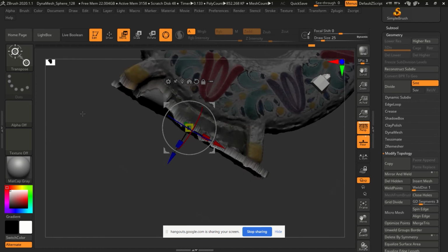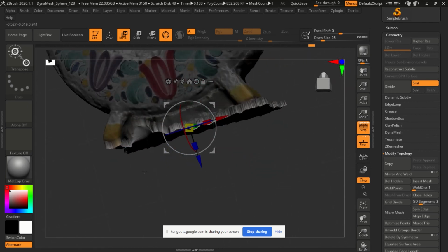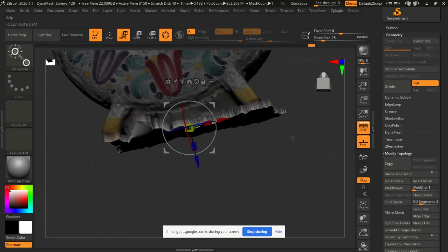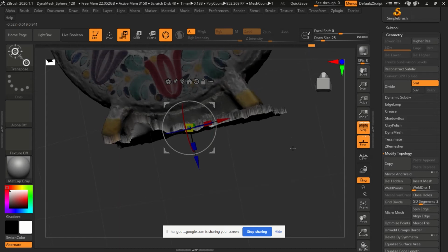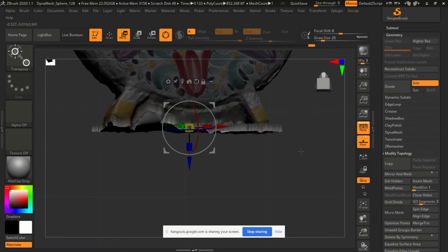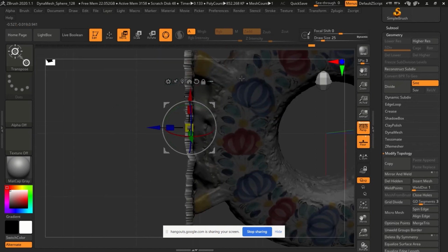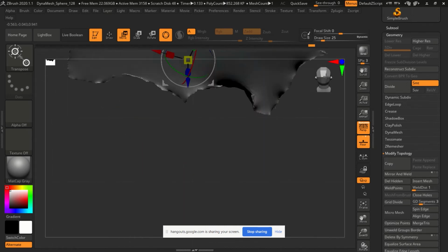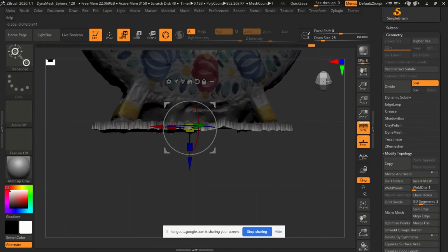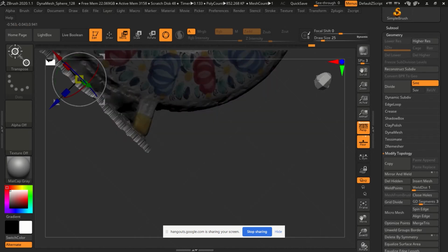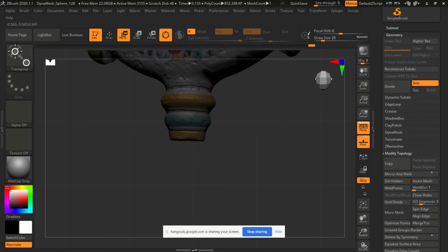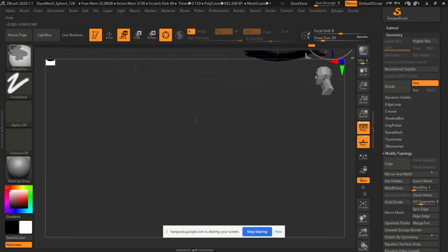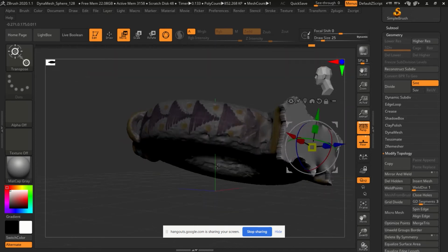If you want to snap to a view while you're rotating, so maybe this is a little annoying, while I'm rotating, holding right click, I can hold Shift and it'll actually snap to 90-degree angles, right? That's similar to what using this model is doing. It's snapping to 45-degree angles, or using those navigation tools as I mentioned before.